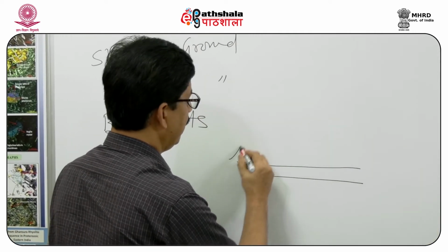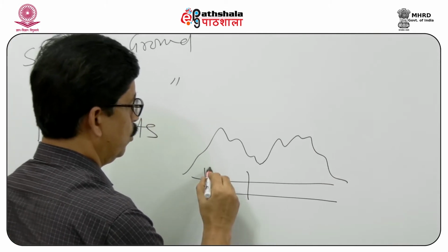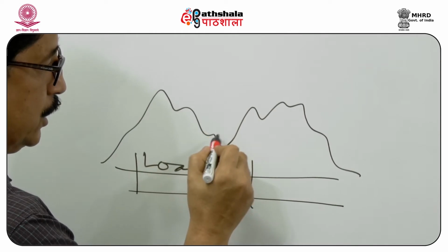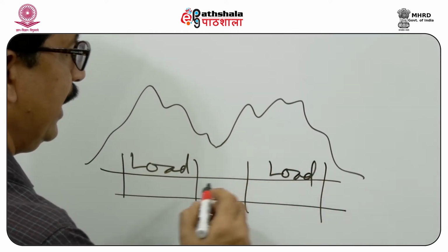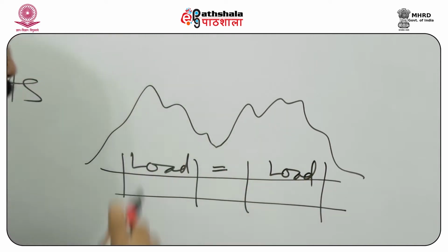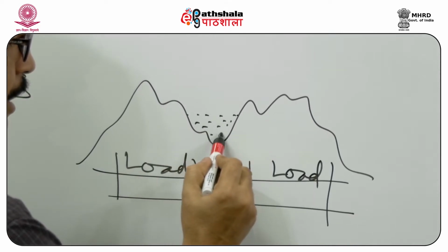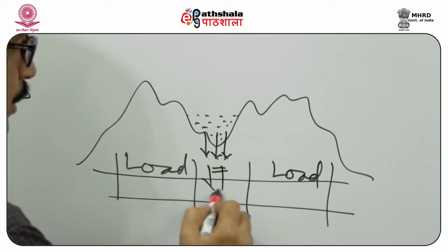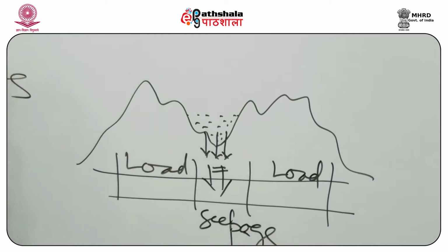Wherever we have high ground, the load will be more as compared to areas where there is a valley. So the load in this section will be high as compared to this section. But if you have a valley fill, then we will have a problem of seepage in this part of the tunnel.